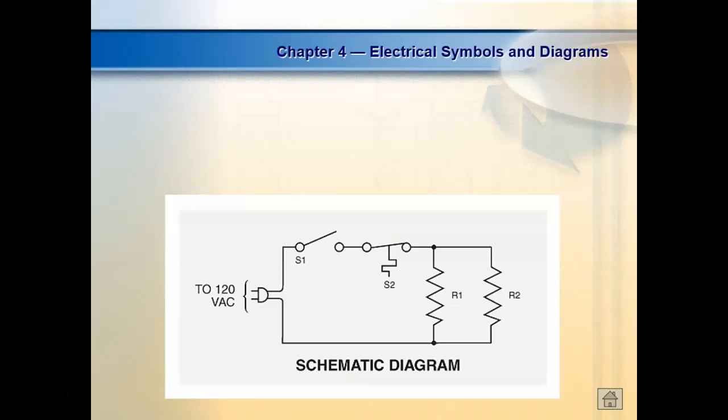And the analogy I use is that when you open up your breaker box or your panel box, anybody ever pull the cover off the panel box? And how many wires go to the breaker? One. If it's more than one, you got a problem. You got an electrician that you should never call back. But it has one because all the jumping in the parallel circuit is done inside your walls, at the outlets, and stuff like that. And you'll very seldom see power sources with more than one wire hooked up to each terminal.